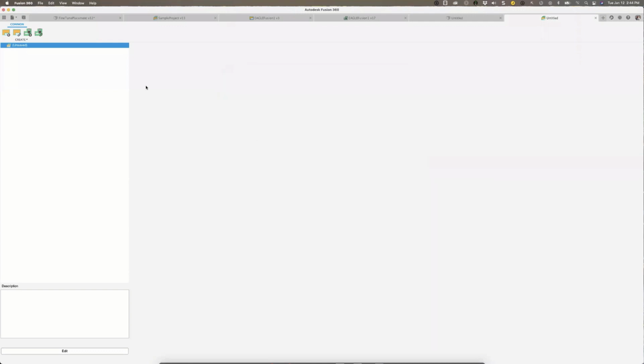Okay. And if you have a board that references that schematic, once you select the schematic, you go here and you reference the board. Now, with that said, in this case, I'm going to start working with a brand new schematic. So to work on a brand new schematic, I will click the plus sign here where it says New Schematic. And this is going to bring me to the schematic editor.